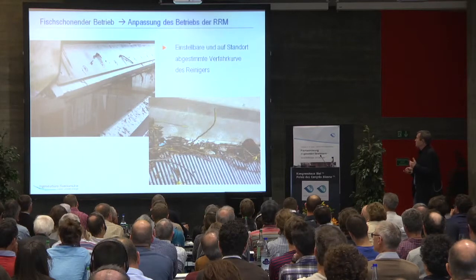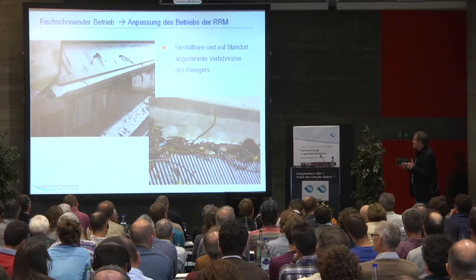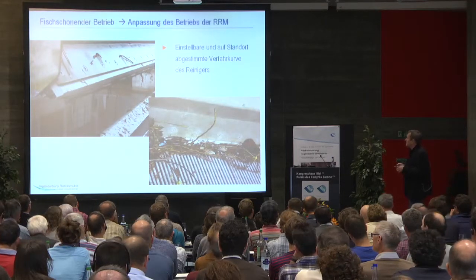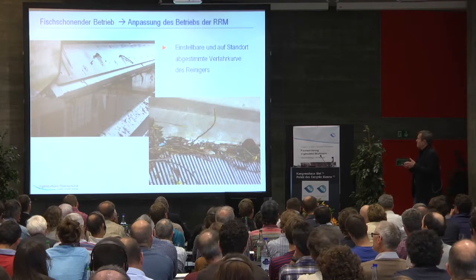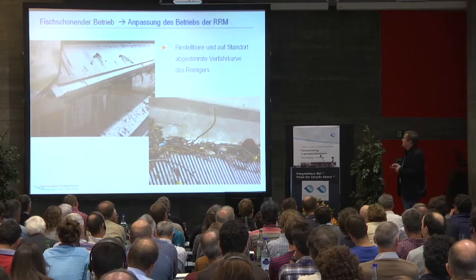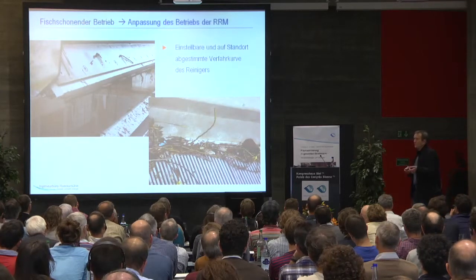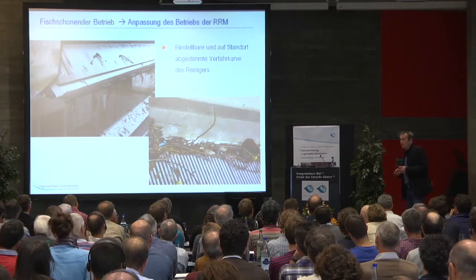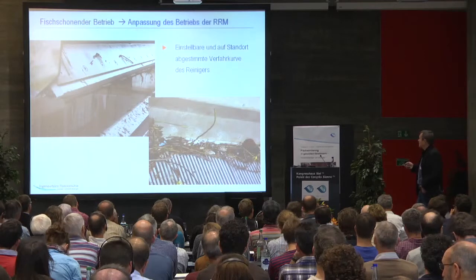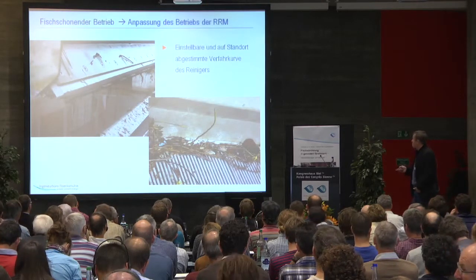We must adjust it to the fish's behavior, because we found that sometimes fish are waiting up in the upper part of the screen. They wait before they enter into the bypass, and if this cleaning device starts at the wrong point of time, this can be counterproductive, but we now have control mechanisms for these screens, and this is no longer a problem now with modern solutions.